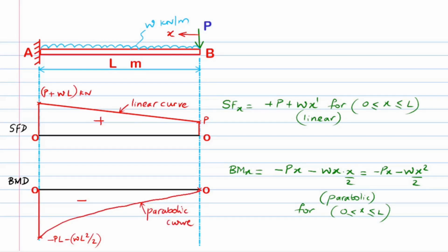By slight investigation, you may observe that the shear force and bending moment diagrams obtained for this case are nothing but a superimposition of the shear force and bending moment diagrams of two cases of loadings that we investigated earlier, which is but a demonstration of the law of superposition applied to linear systems.